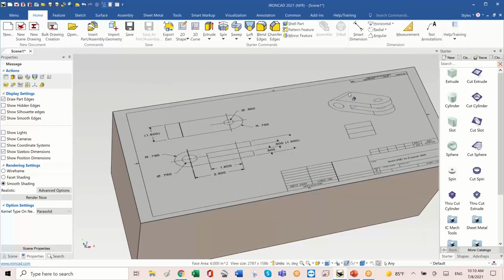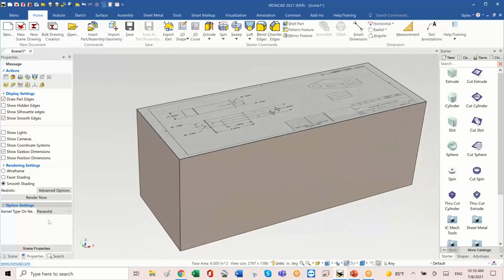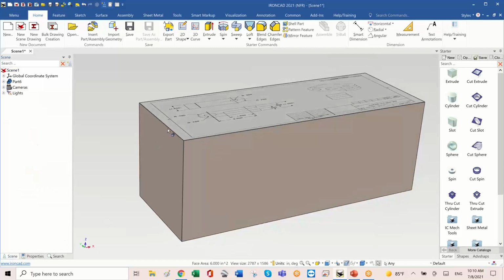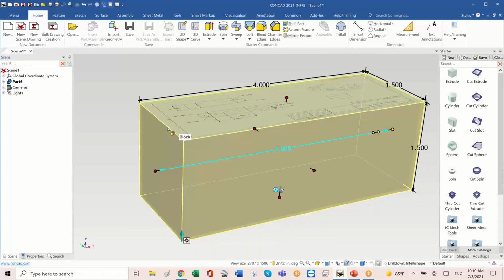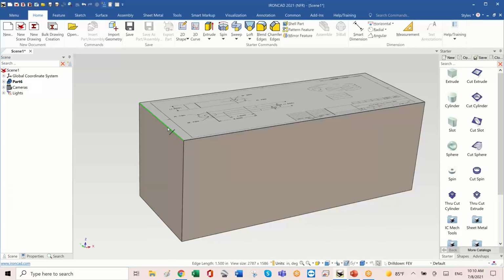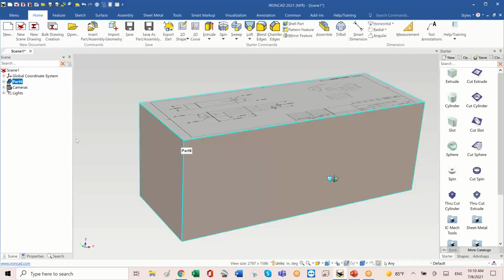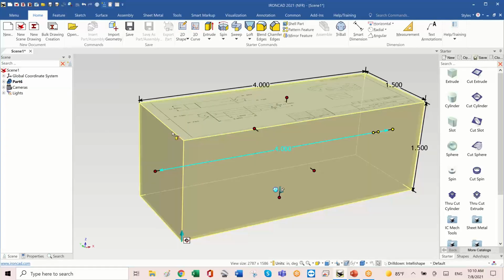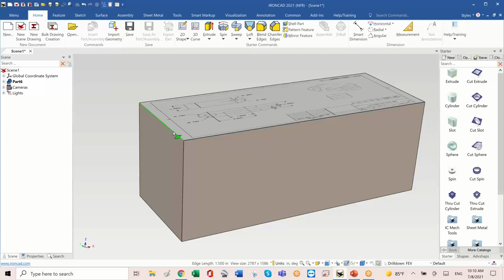Well, I need to make this part, which means I need to make the rounds. So let me look at this part and pick on this and see what I can do with a line. By the way, I kept clicking, and I want you all to know how I did that. I clicked on the part once. That brings me to the part level. I clicked on it again, which brings me to that IntelliShape that lets me make my changes. If I click on it a third time in a specific location, it drilled down into the actual geometry that I'm pointing at.